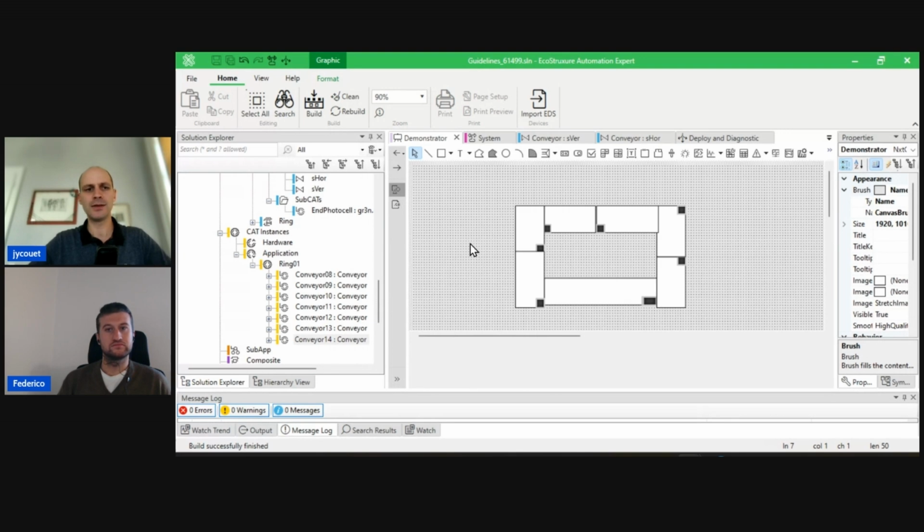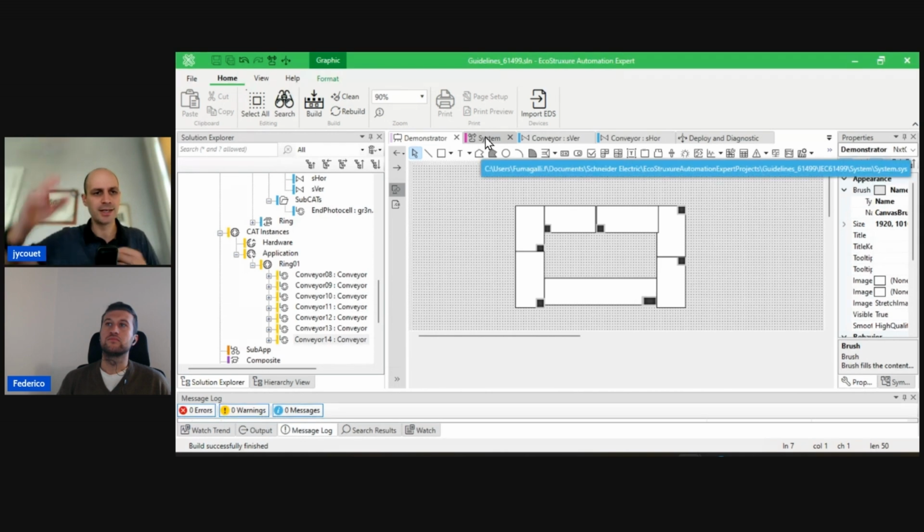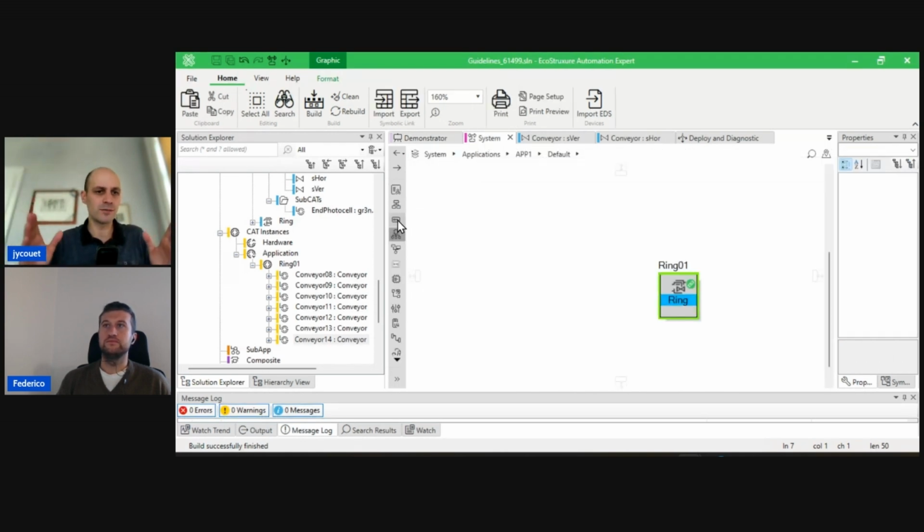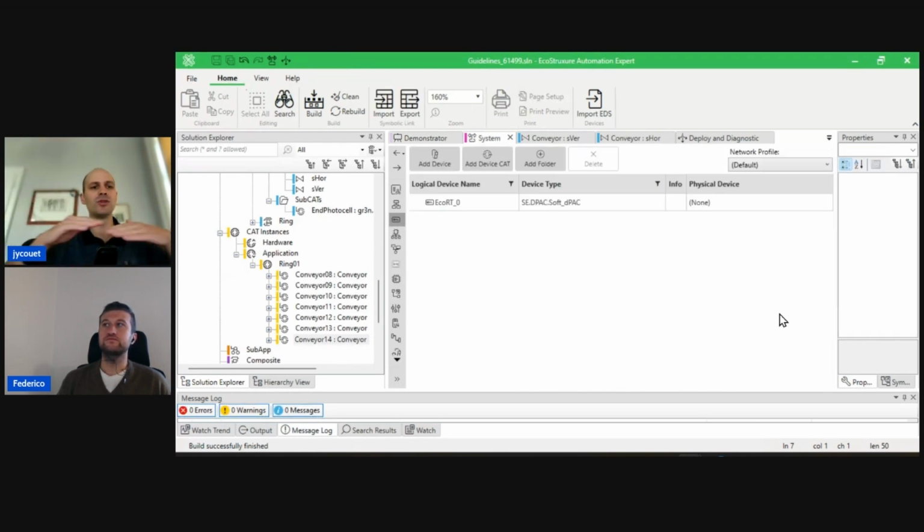the HMI, I want to say a few words about vertical slicing. What we do here is that we do a minimal set of application, but we try to deploy it until the HMI. And this is what can be called vertical slicing, meaning that we don't start developing the whole code in the PLC, then the code in the HMI. No, you take few small functionality in a vertical way, and you try to deploy it fully. Like this, you did all the steps, and then we will add functionalities.